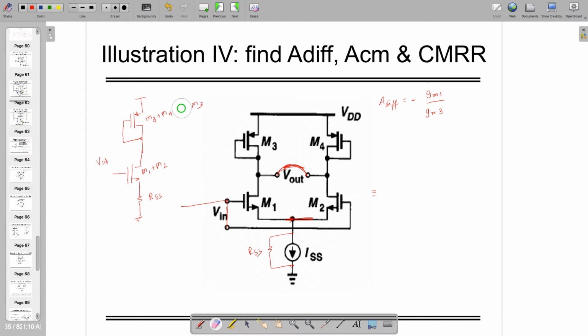Yeah, so this is going to happen. I cannot write down M3 because this is going to happen in the case of GM only. And if I'm taking the output from here, what is the common mode gain? The common mode gain will be coming from here. It's nothing but a simple one. Looking upside, there are two diode-connected transistors in shunt, so each one of them is giving you 1 by GM, so it will be a total of 2 by GM.